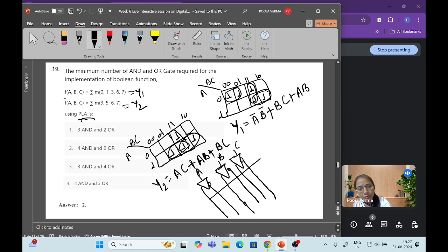So now the AND gates. First here the terms AC, BC and AB are in both, so we can take one each. So first I'm taking AC, so A and C. Output of this AND gate is AC.